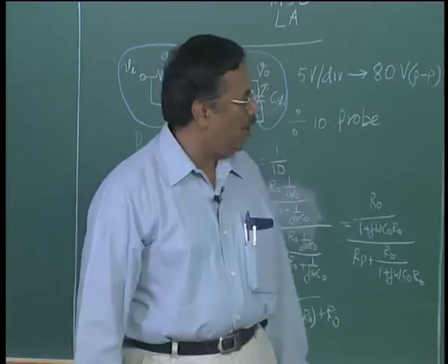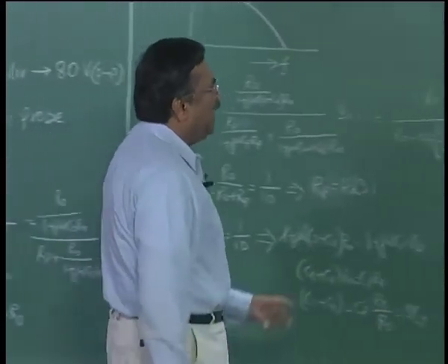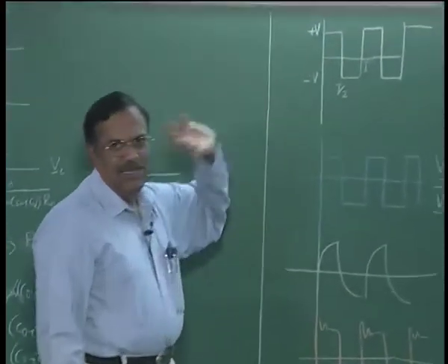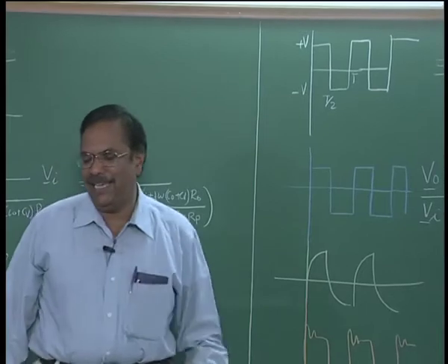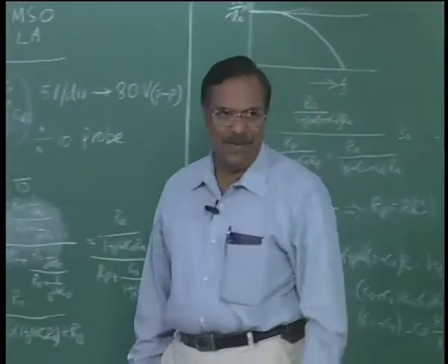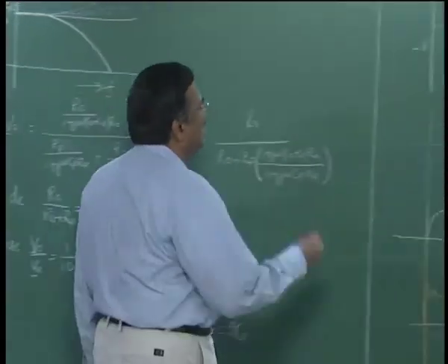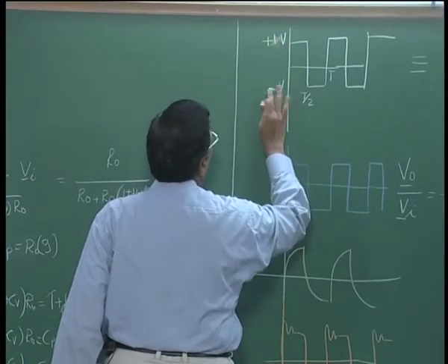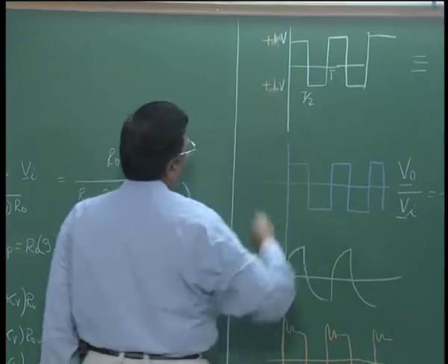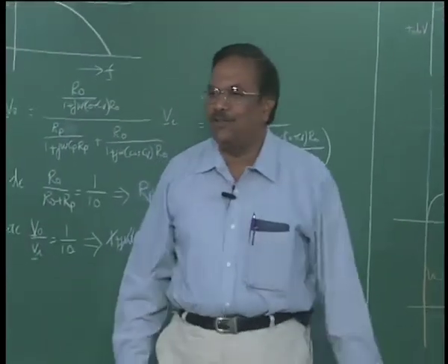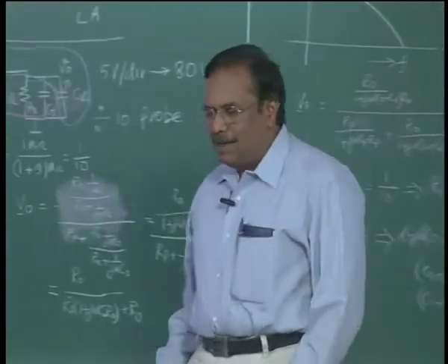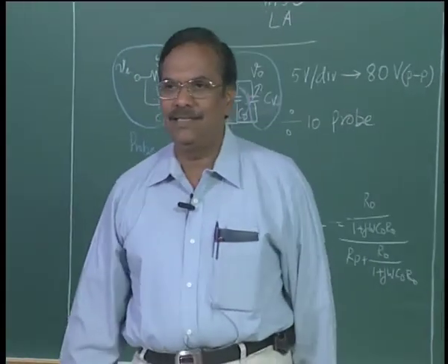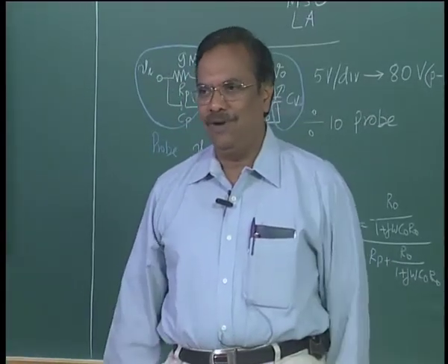All oscilloscopes provide an output of 1 kilohertz, and because they anyway provide an output of 1 kilohertz, they also make it 1 volt instead of any arbitrary value, right. It could be 0 and 1 volts, or plus 1 volt and minus 1 volt, depending upon the manufacturer, but it will always be 1 volt, right.